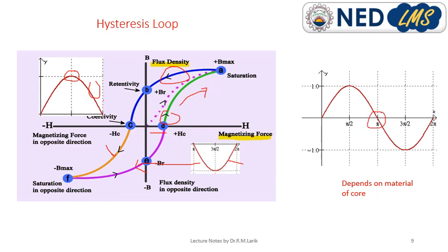See, when the current reverses at this point, the magnetomotive force also reverses, the flux reverses. So reversal of magnetism is permissible at some cost actually. That cost is loss. Reorientation of magnets means the magnetic domains are aligned in one direction due to the positive cycle. Then the magnetic domains are realigned again in the negative cycle. So reorientation of magnetic domains at some cost is hysteresis loss. At this point some losses occur, which is hysteresis loss.